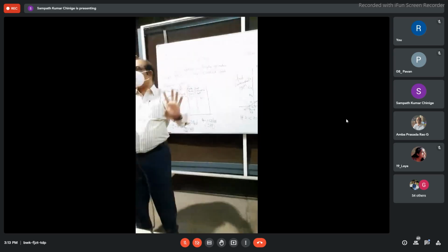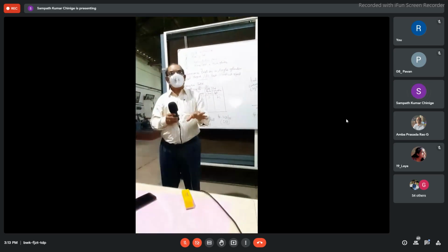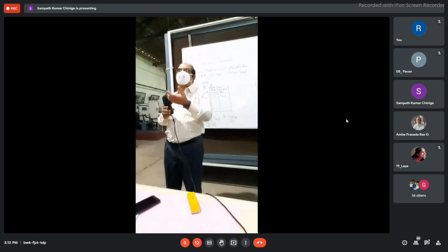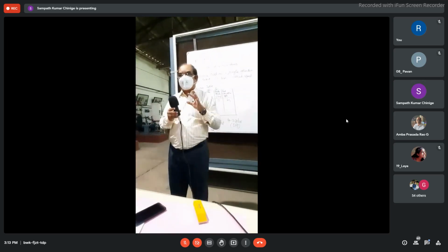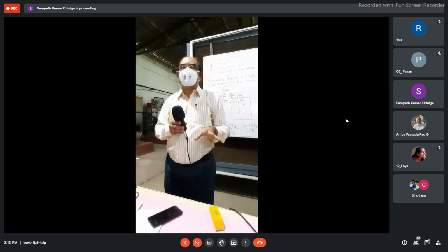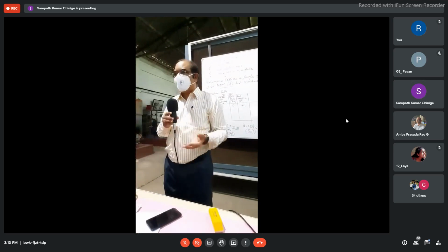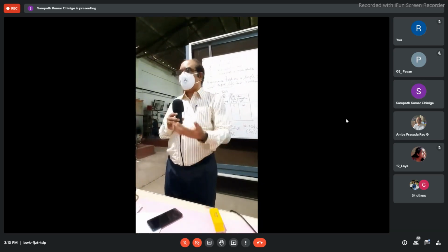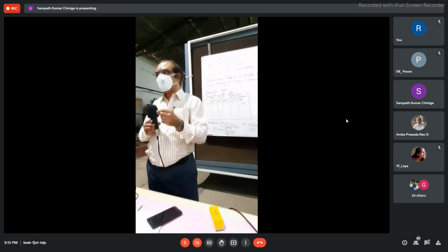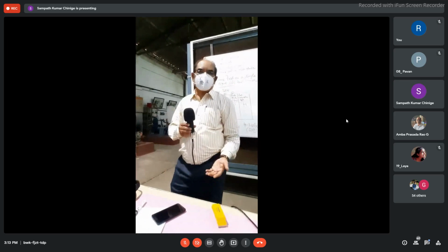You know pretty well that the motor may not be working with 100% efficiency, so it will have some motor efficiency. Whatever power value we get is divided by that motor efficiency, so actually it is drawing that much power. Please note here that we are running the engine without supplying fuel, so the engine will also be running without taking lubricating oil. If we run for more time by taking power from the external source, we will be unnecessarily generating more friction. So the only caution here is to complete the test as early as possible so that the friction will not build up.